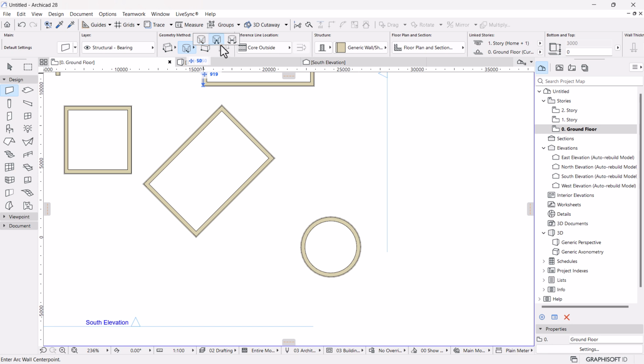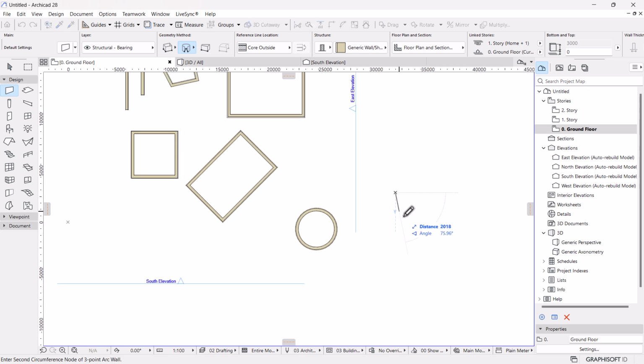The second one, you have to specify the first point, the center, then the distance. Let's key in 5 meters. Then I can specify another tangent of 4.5, like that. Then I can close up the circle.